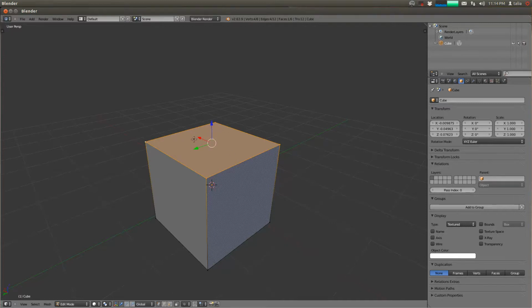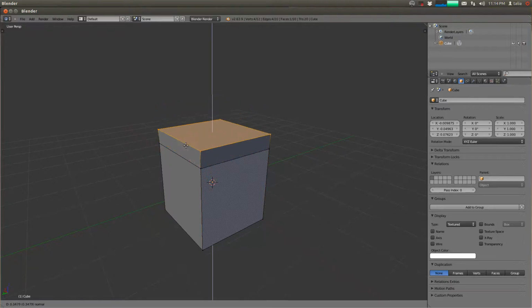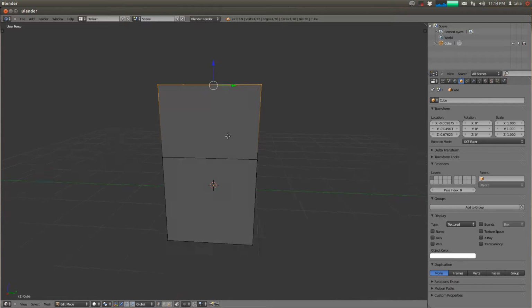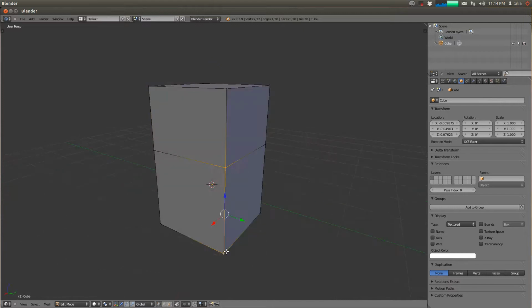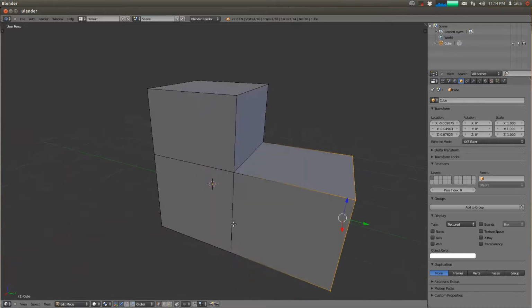And you need to remember that each one of these is important for certain types of operations. I'm just going to mention one of them real quick here. I'm going to hit the E key, and E starts an extrude operation. Now I'm just going to move the mouse up and down a little bit, and if I left click, it's going to confirm the operation. Extrude basically works on any face. Let me do it over here too, just to illustrate. So E, pull the mouse out, and left click to set it.